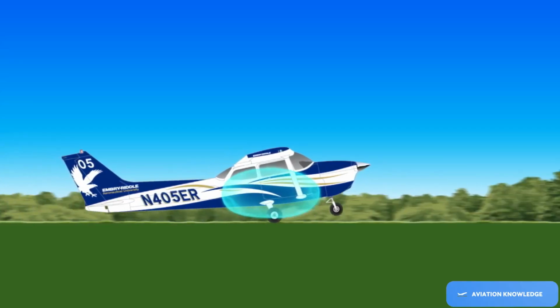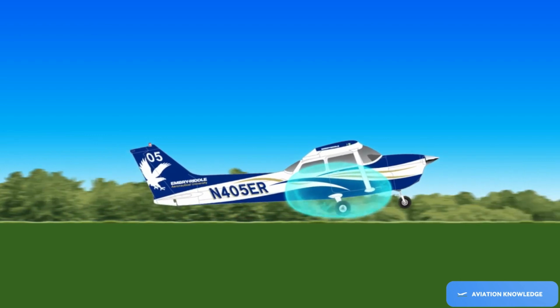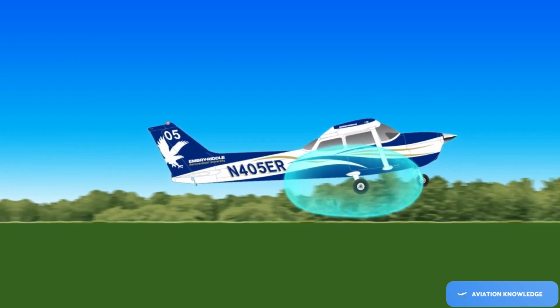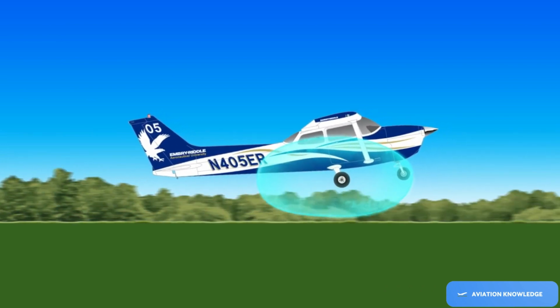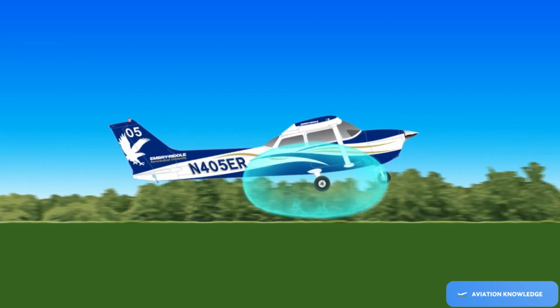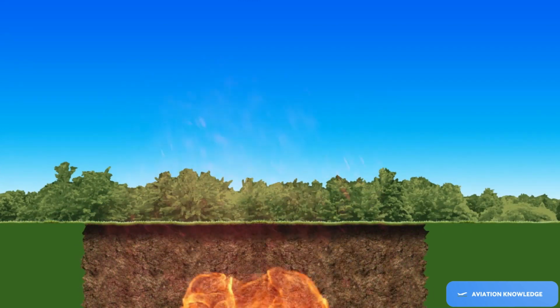Because of ground effect and the use of flaps, the airplane will most likely become airborne at a very low airspeed, even below stall speed. You do not want to climb out of ground effect, or you could stall the airplane, and since you'd only be a few feet off the ground, well, that would not end well.